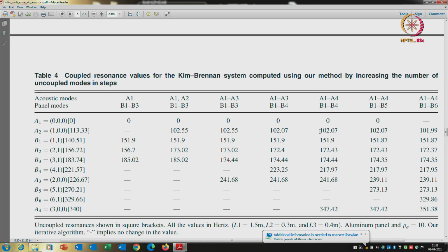So as omega n becomes larger and larger for a higher mode, their influence becomes less. If you are at B2 or B3 around 150 and you start taking in resonances of 300 or more, their influence will die down. So a coupled value settles down quickly.